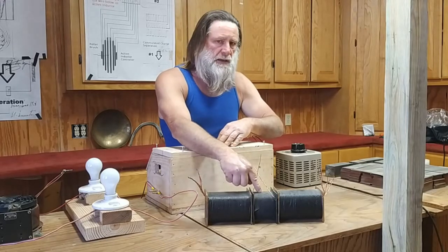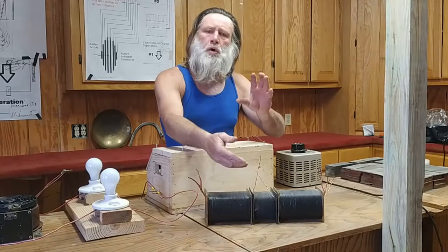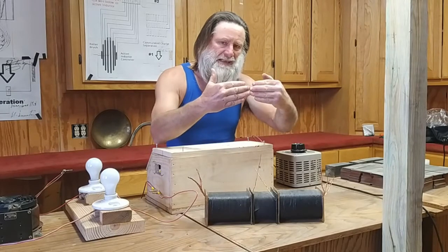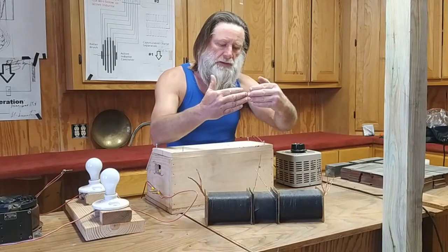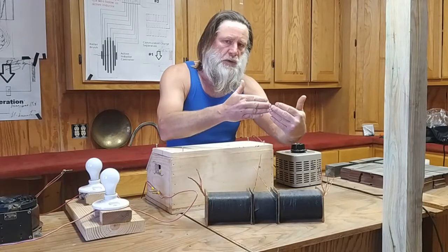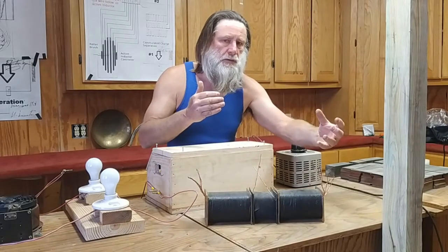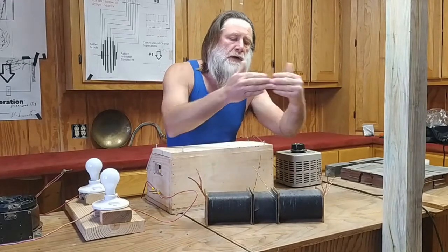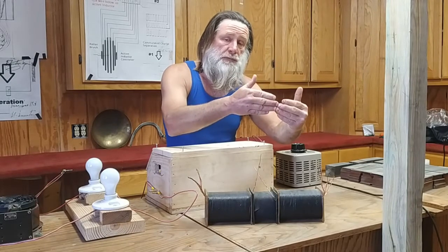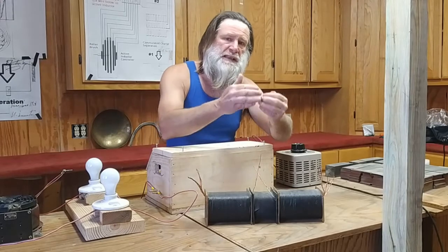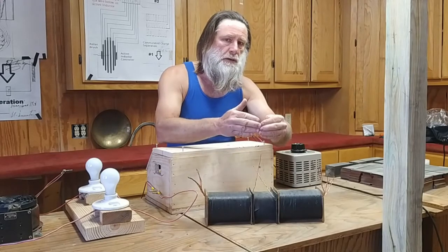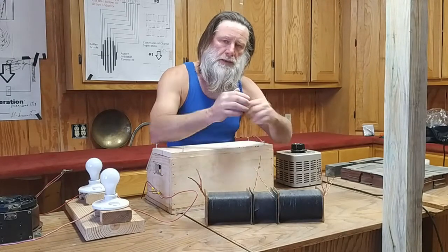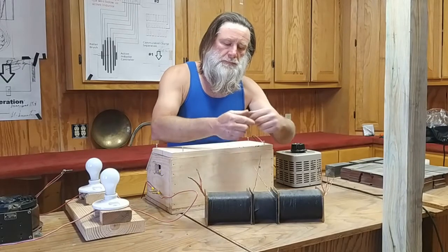Once you polarize the secondaries and current begins to flow, according to Lenz's law, a second field will form. It's that field that is sandwiched in between the two primaries. When you reduce one to get the sweeping action, you're actually creating an electric field. The increasing one is shoving that opposing field across that electric field. This gives the illusion of motion. It's virtual motion, but it's still motion according to the laws of physics, our universe.